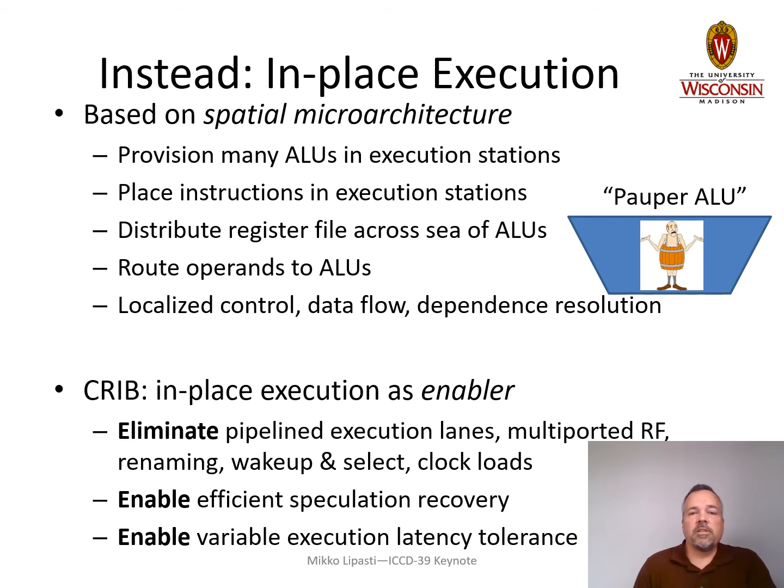Let's route operands to these arithmetic logic units. And then let's implement localized control, data flow, and dependence resolution mechanisms that are easy to design, easy to scale to larger designs, and don't introduce any critical path delay problems. And also, by the way, consume a lot less energy. And so this is what we did.